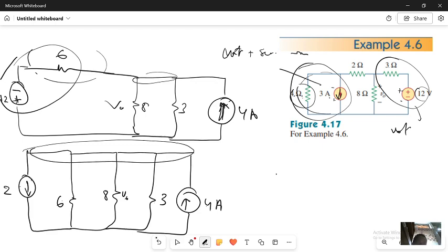In this case, I can apply what? KCL. We know KCL, we know all nodal analysis are almost the same. Here, this current is entering. Since this current is entering, I will have 4 equal to the currents leaving. This current will leave, this current will leave, this current is leaving again. So I will have equal to 2 is leaving, plus the voltage of this one, the voltage of this one. These are the same node, which is V0, because V0 is the voltage across the 8.